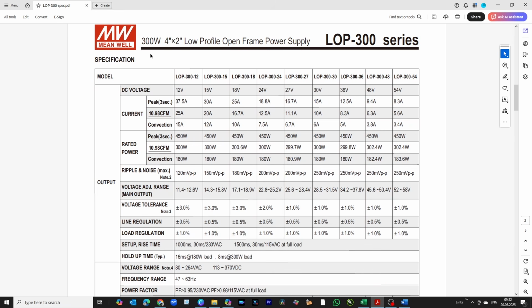So this model, produced in large volumes, has several standard output voltages, and I'm personally interested only in those two. This LOP336 fits very well for a 4 ohm load, no fan operation. Because then everything is balanced, and it can provide at a peak for 3 seconds 12 amps. It perfectly fits. You remember this table, you can go back and look at it. This peak amp capability is really important, and this power supply can do that.